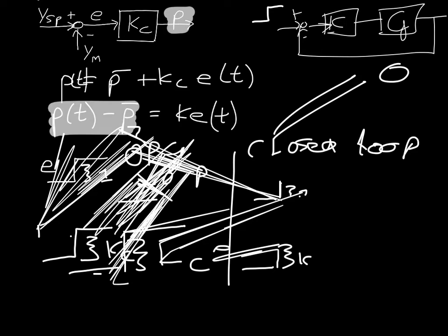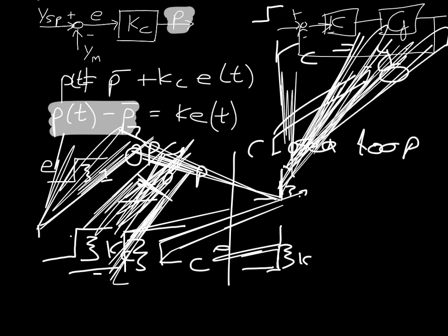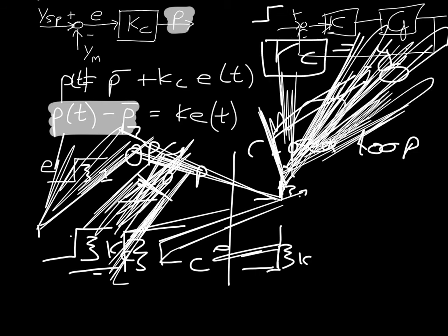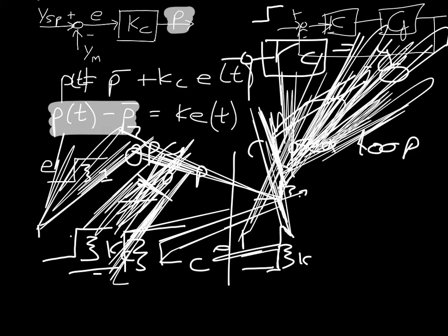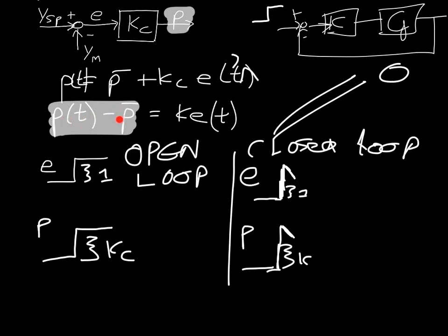But the difference is that as soon as we make this step change, and as soon as the controller starts taking action, the error will become less. And why is this? Because the system is now moving towards the set point if we've chosen the gain correctly, and so therefore the error will become less. What that means is the proportional action will become less. And if you think about it, that means we're talking about this thing, right? Because these two things go together. The error here leads to a proportional change. And we're moving back, in other words, towards the original bias position.